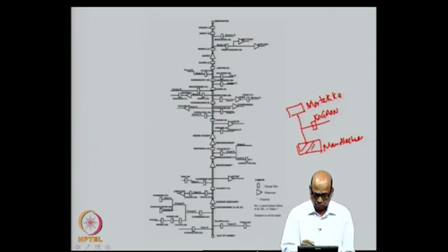We will see subsequently what is to be done with the reservoirs and how to compute the normalized flows, but assume that you have normalized flows. By normalized flow, I mean that the effect of the reservoir has been taken out and the flows have been converted into a naturalized flow series. So, if you have flows at this location, this location and this location, you can examine the consistency of the data.